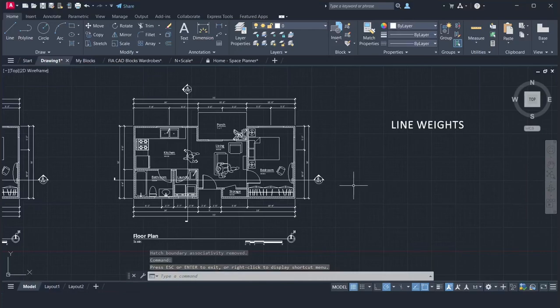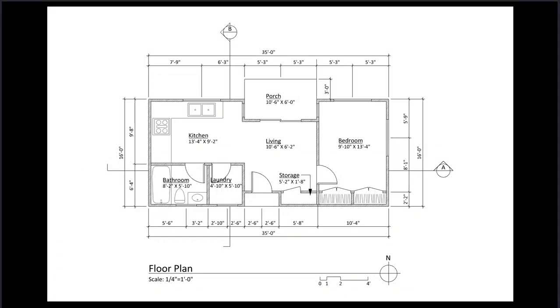Line width refers to the thickness of lines in architectural drawings. Different thicknesses represent different architectural elements and the relationship between the elements. Proper variation of line width could turn a basic architectural drawing into a presentation quality design drawing that communicates design intent. Usually, we use light lines for details, mid-width lines for openings in walls, and heavy lines for sections or cuts.